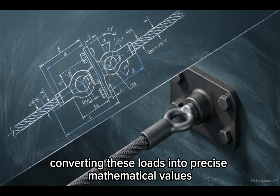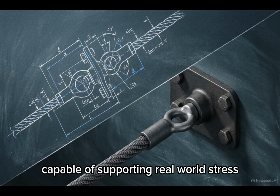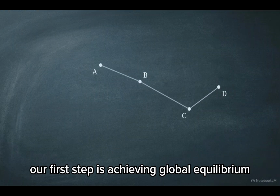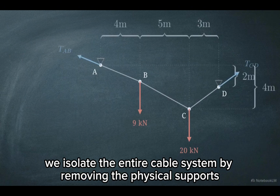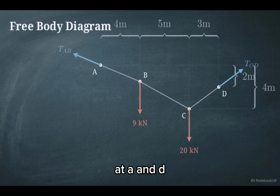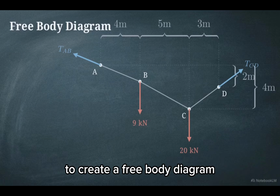Converting these loads into precise mathematical values allows us to move from a theoretical sketch to a physical design capable of supporting real-world stress. Our first step is achieving global equilibrium. We isolate the entire cable system by removing the physical supports at A and D, replacing them with tension force vectors to create a free body diagram.